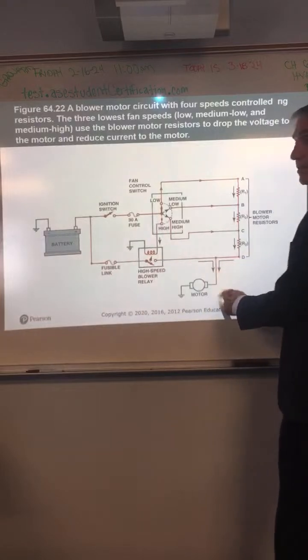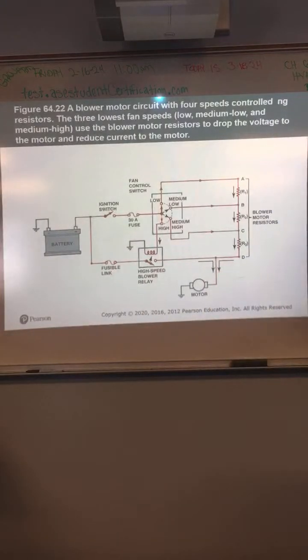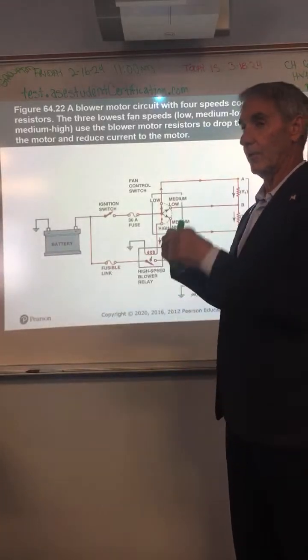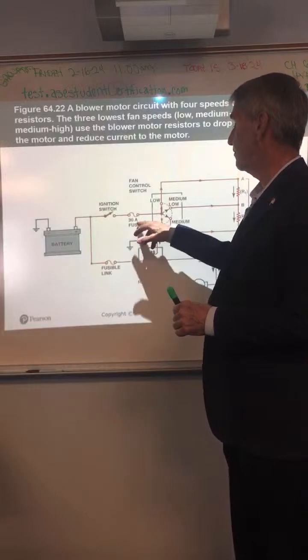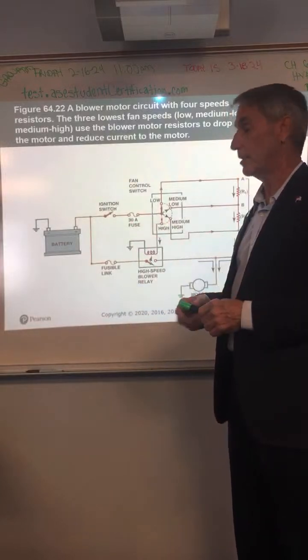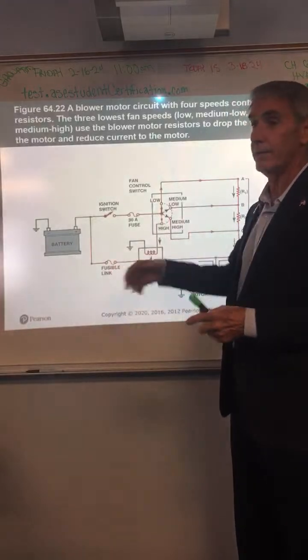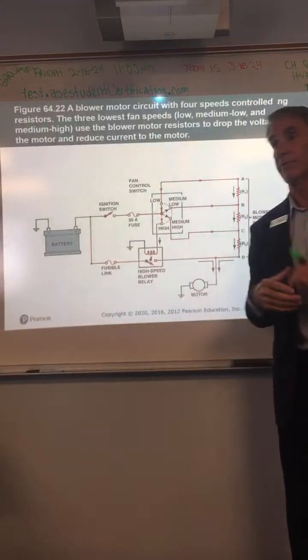Oh, so that's why. Is the fusible link the same thing as a fuse? It's just a wire, whereas a fuse is actually a fuse. A fusible link, if it goes bad, it just melts a wire in half. It's a special wire that's designed to melt if the current flow is too high.